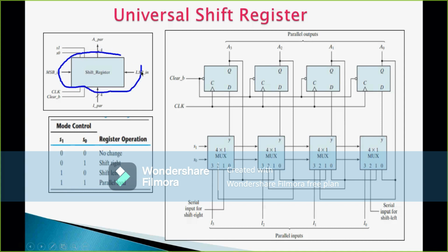So I hope you understood now the block diagram of the given circuit, right? The block diagram of this universal shift register is given here. Now see in this circuit how the operation is. Here we have to use the multiplexer, because this multiplexer accepts 4 different inputs. It has 4 pins as inputs. Multiplexer we studied in unit 2. It will accept 2 power n inputs, and only one output will be directed. The selection line also will be there. 2 power 2 equal to 4, so 4 inputs means 2 selection lines will be there. That is what we have here as S0 and S1, right?